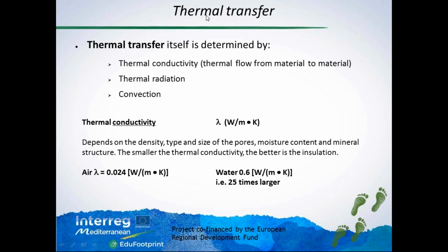Yes, just to recap, the thermal transfer can occur as thermal conductivity, as thermal radiation, as thermal convection. And in the materials of the building, the elements of the building, the very important characteristic is the thermal conductivity of the elements. This is the so-called lambda factor, and it depends on the density of the material.